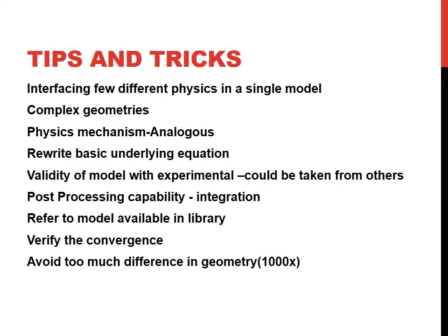Another tip is that with the FEM software, you also have the possibility to do post-processing of the results. So for example, you can show the result differently by doing integration or derivations, or by doing some mathematical operations, and also graphical operations.